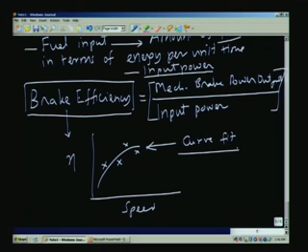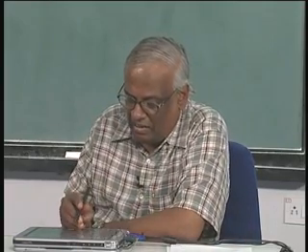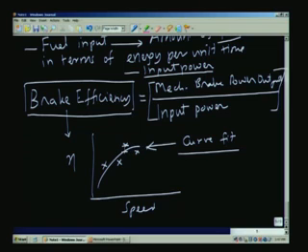Therefore, in any activity which involves measurement, including the characterization of an engine, we can talk in terms of fitting the curve, and then talking about the variations. For example, you can see these are the error bars. You can see here there are errors. We can find out what is the variance of the eta, or the standard deviation of the eta which we are measuring, and therefore, it contains a lot of wealth of information, and that is possible by making measurements as we have discussed here.